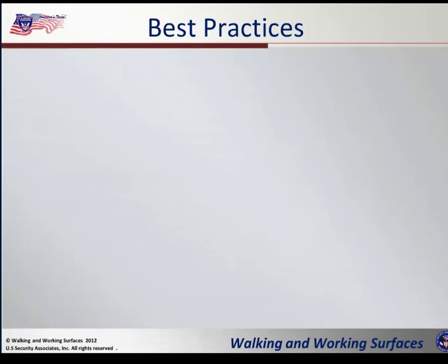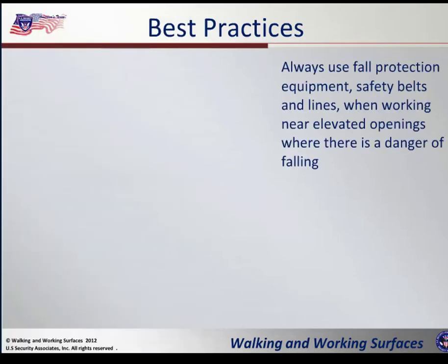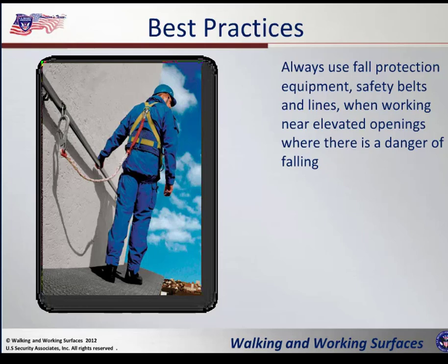Okay, let's take a look at some best practices. Now, these are OSHA requirements that you need to ensure are being followed. 1, always use fall protection, right? So again, OSHA requires that fall protection be used anytime you're working near an elevated opening or where there is a danger of falling.